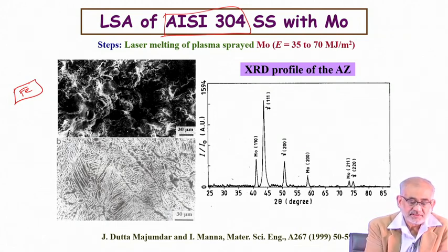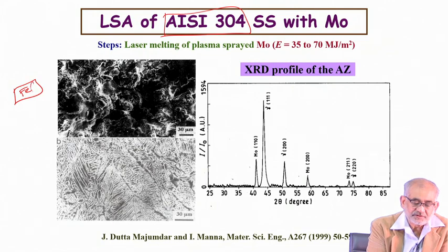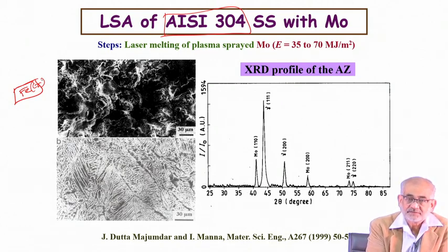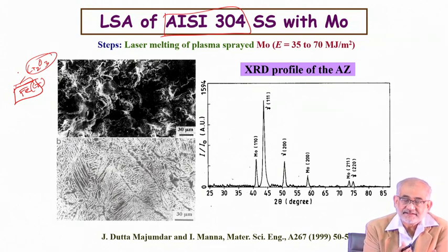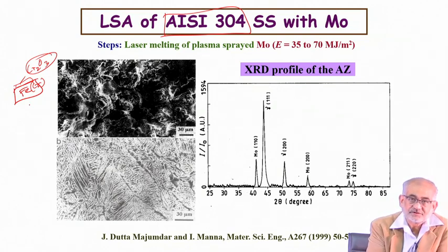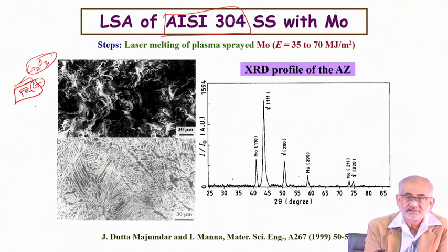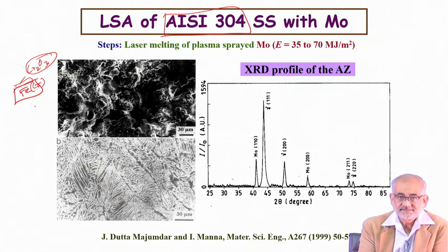We see rusting. In order to prevent rusting, if you alloy this with chromium, this chromium actually sits throughout, but the chromium atoms at the surface will immediately form a protective layer, which is typically a chromium oxide layer, and this is a fairly adherent layer. So it prevents any further oxidation, any further corrosion, and doesn't allow rusting to proceed at all. So we get a rustless or stainless steel.